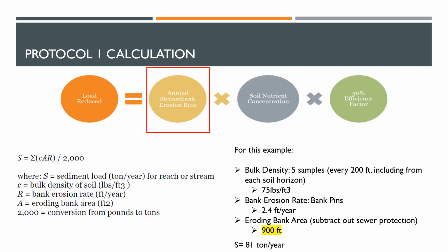Now this is a little oversimplified because I'm treating the rates as the same across the entire reach. Generally, if you have a contractor doing this project, they're probably breaking this down. You're going to have different erosion rates on different meander bends. The outer bend of the meander is going to be eroding much faster, so they're going to be focusing on those areas, and that's why it's the sum of these different segments. But for simplicity, this is how we're going to do it for this calculation.